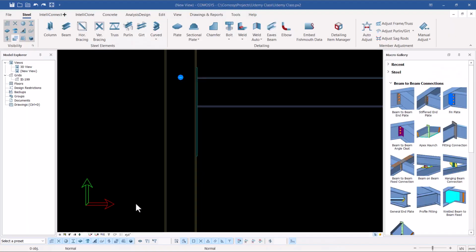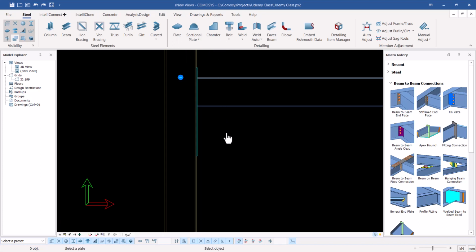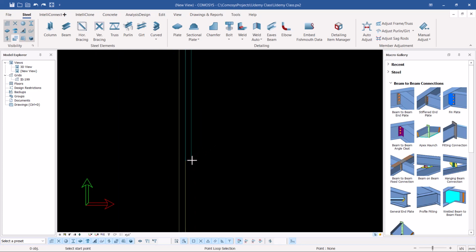Welcome back, and we're still on the sectional plate. Now we want to create a haunch here. So prior to creating a haunch there, on the sectional view, I'll come to plate, pick on the sectional plate, right click. Then I'll just mouse over the edge of the plate we had created previously, and just mouse over that spot. Then enter on my keyboard right, like that.